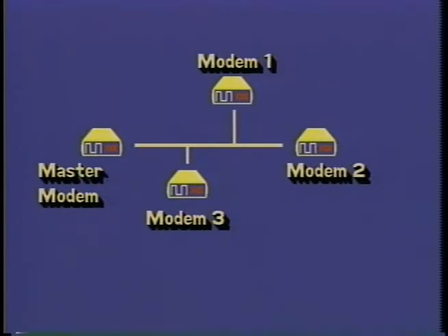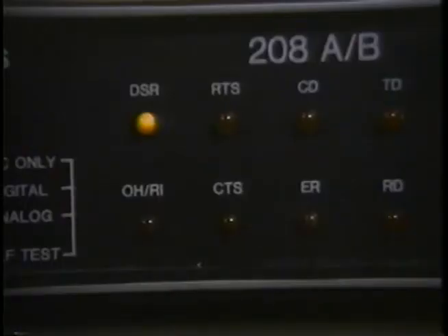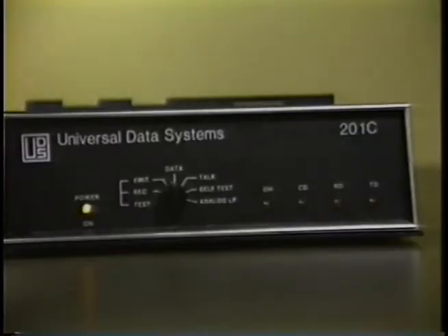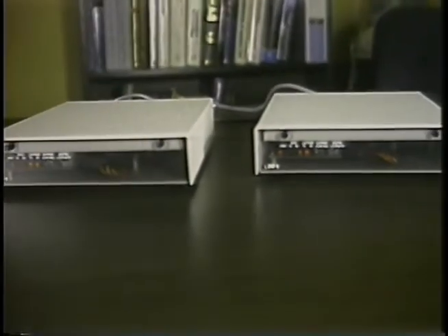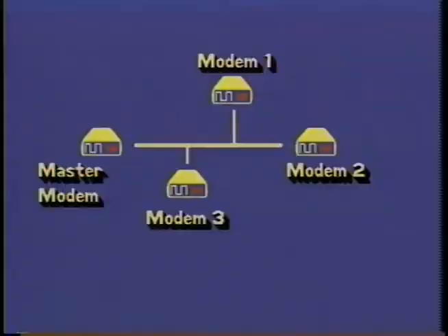For multi-point modem operation, there are two key options and a third option that is becoming more common: controlled or constant carrier, request to send, clear to send delay, and streaming modem disconnect. Constant carrier is used for point-to-point four-wire operation of modems. Controlled carrier must be used for all 201, 202, 208, and 9600 modem two-wire dial-up applications, and on all remote modem stations on multipoint lines.